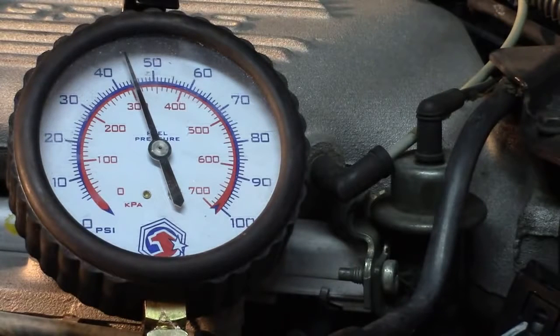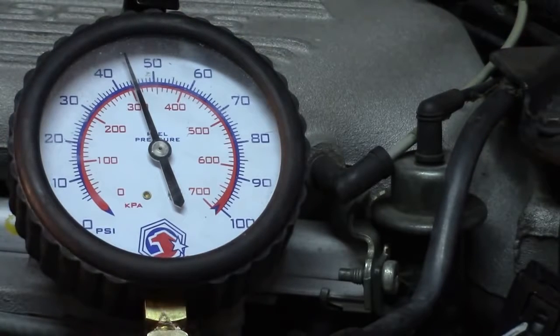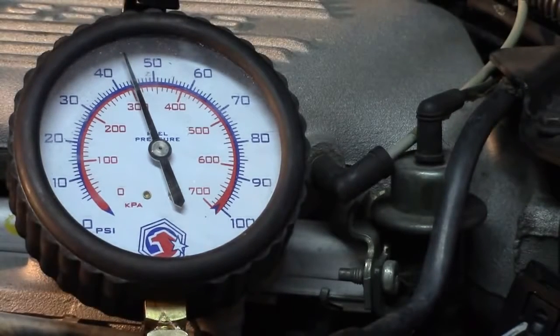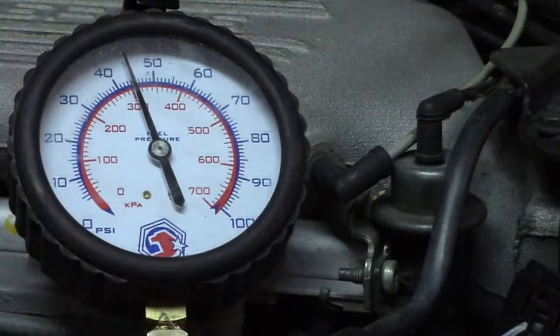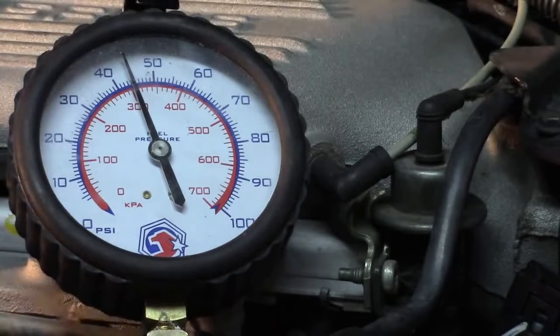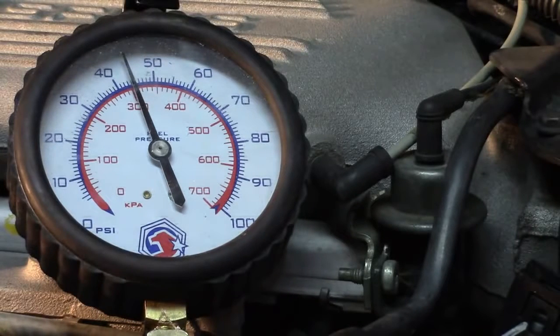Now what I want to do is check really quick at my Schrader valve connection and make sure we're not leaking fuel. Obviously we're not because we're holding pressure, but I just want to be extra sure here. If we were dropping pressure here, that would be much more of a concern. And there's no fuel leaks or anything as far as my connections. So what I want to do is wait a couple minutes here and see if that holds. Okay, so after a few minutes, we can see that we are still holding very strong at that fuel pressure.